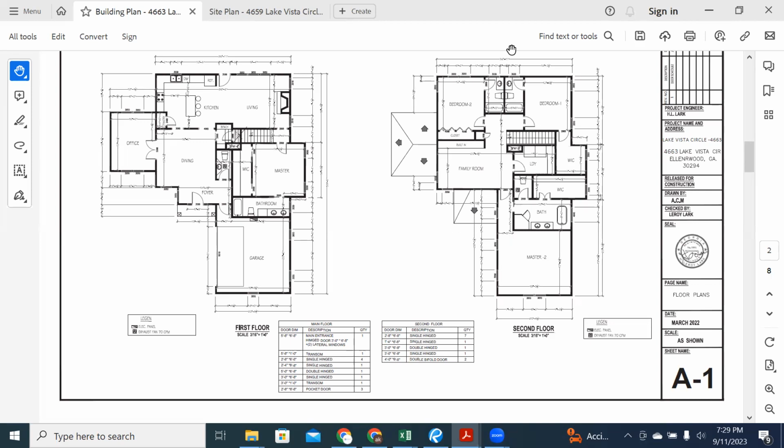So never mind that you got your roof, which is sitting on this second floor, okay? But you have the weight of the walls on this second floor. All of this has been transferred over to this first floor. So the walls that are here on the first floor, this wall, this wall, this wall, this wall is sitting on these, okay? You have these walls, these are sitting on them.